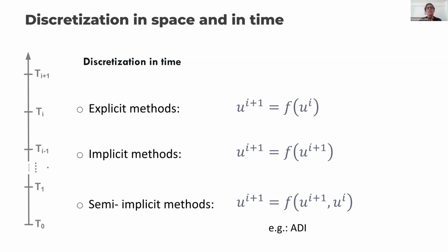Obviously, we are always trying to increase the delta t, because if we increase it, we have fewer iterations, and so our model runs faster. So we have a faster solution, or for the same time, we can have more cells, a higher resolution, okay?